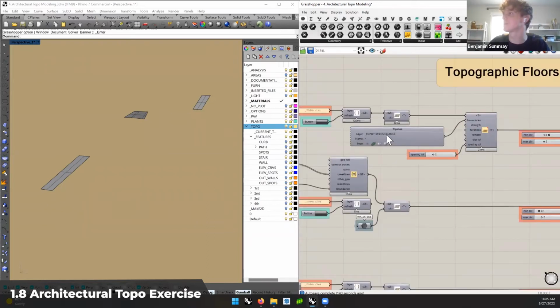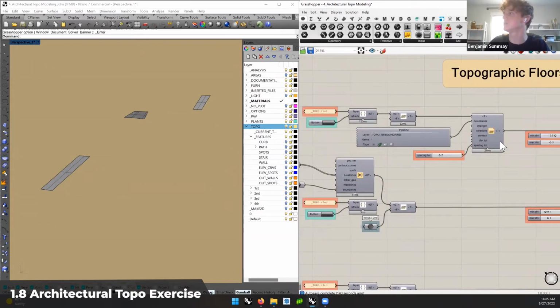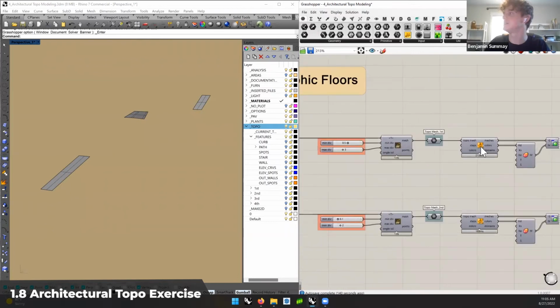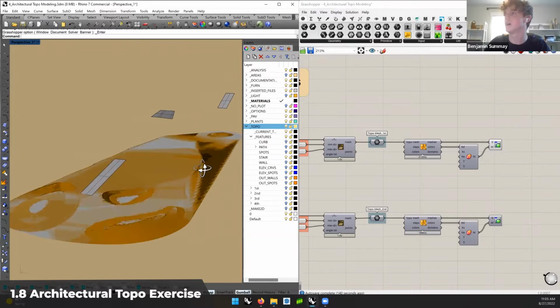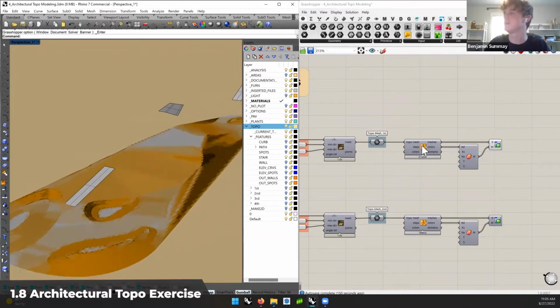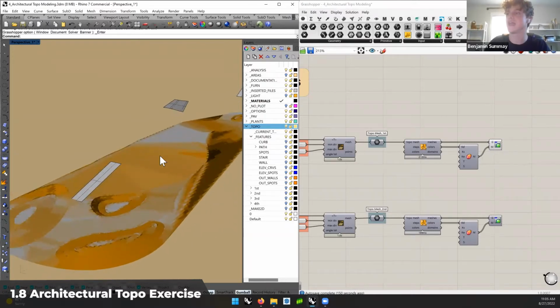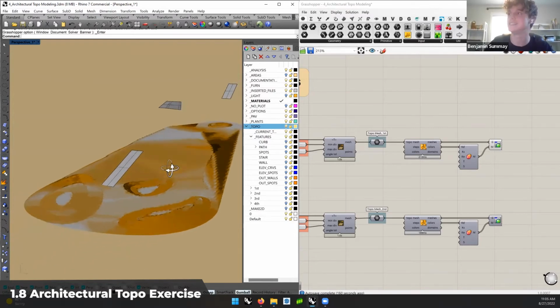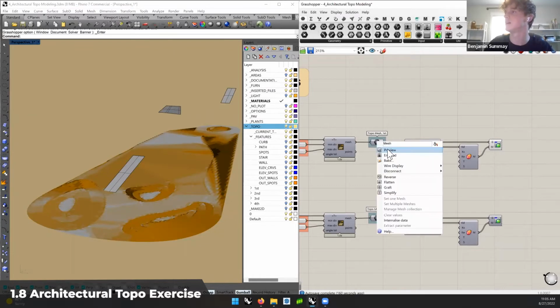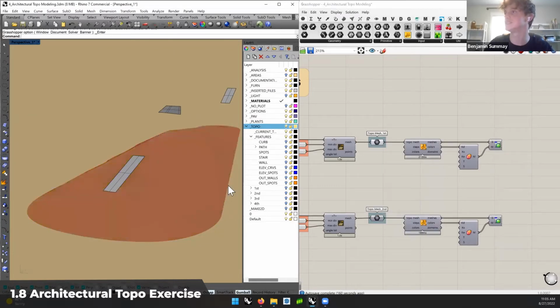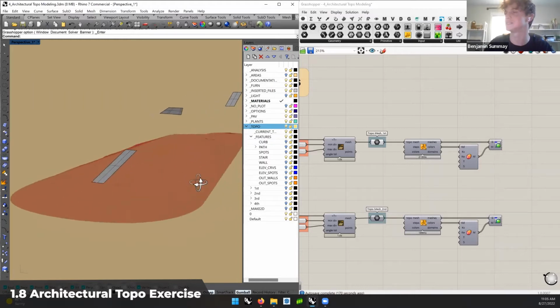But the first thing we're doing here is simply creating a piece of topography that represents the first floor. And so I'll turn this on. I was using the slope analysis here to analyze the steepness of these different slopes and these ramps, so that I can ensure that they're walkable going up to the middle of this first floor, so that it's easy to make the second floor ramp accessible. But if I show the whole mesh here, you can see that it's encompassing the entire space.